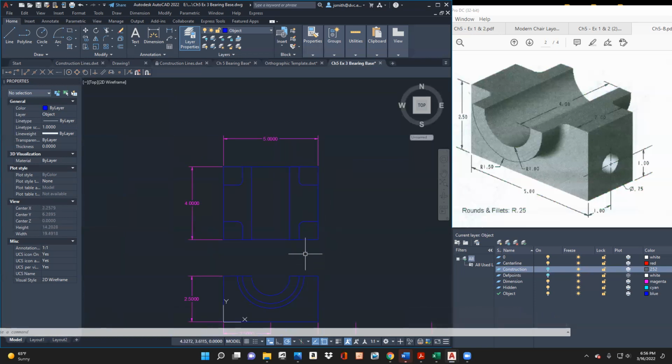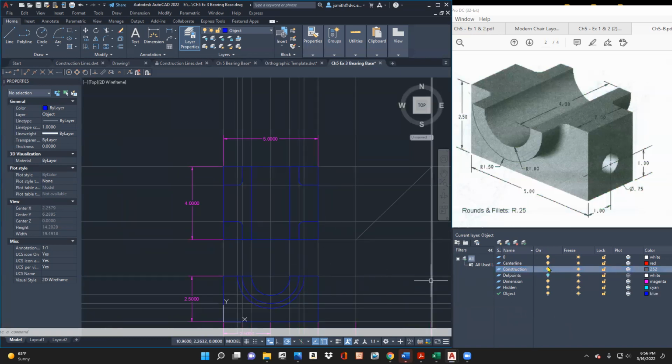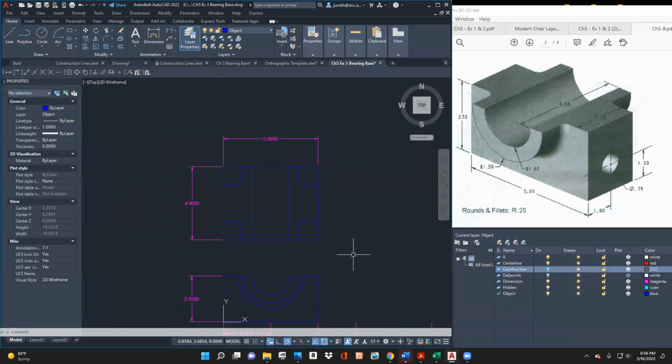And so you'll notice that's the radius. If I turn the construction line on, you'll see that's what we're seeing. All right, so turn the construction line off there. Now I don't need this line here, so let's go ahead and do trim again. And again, it's hard when you've got the construction lines because it actually will stop where the construction lines are. So that can be rather challenging.